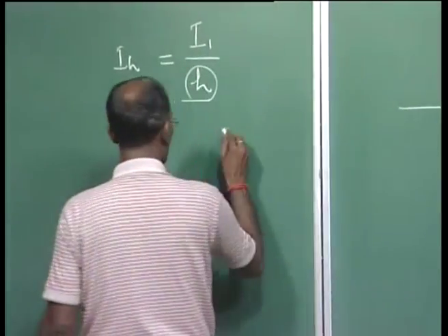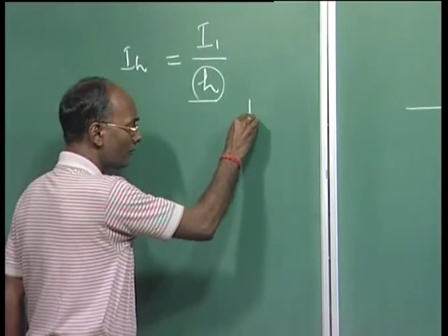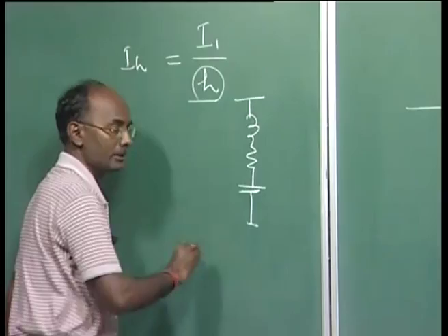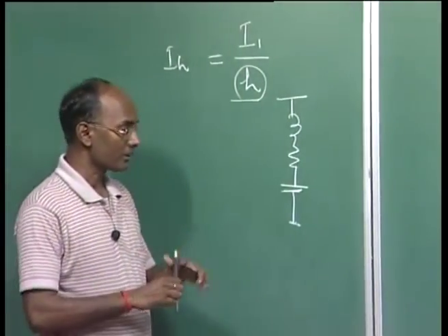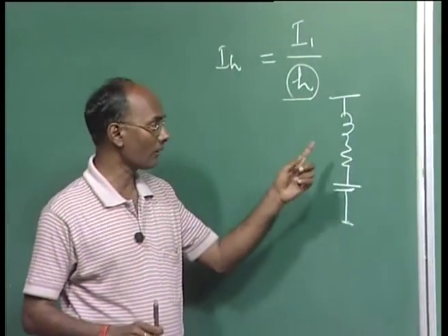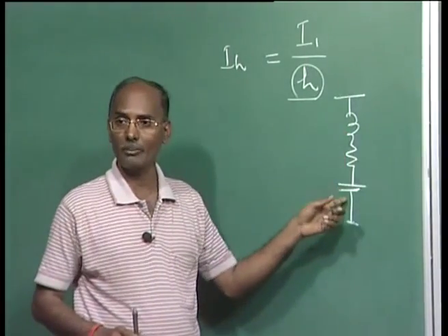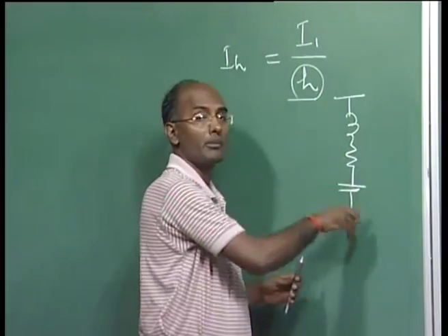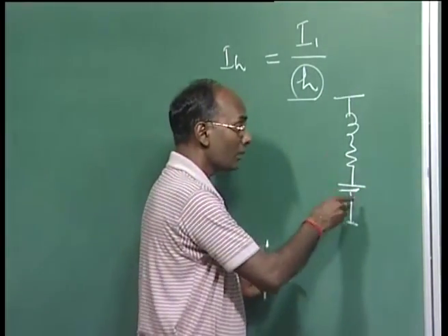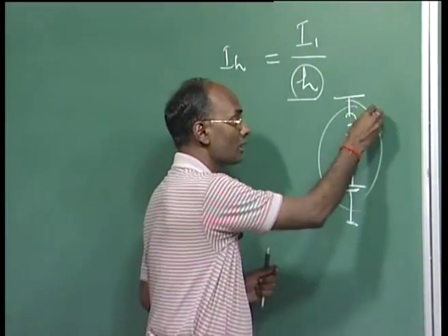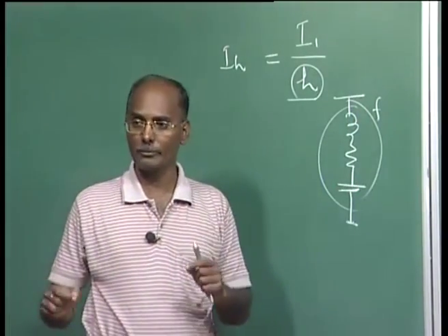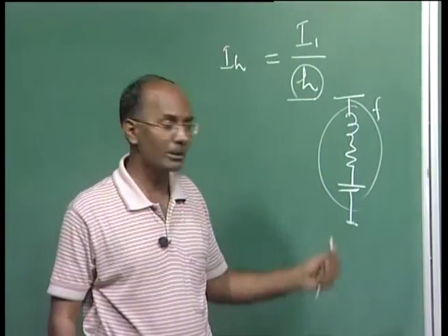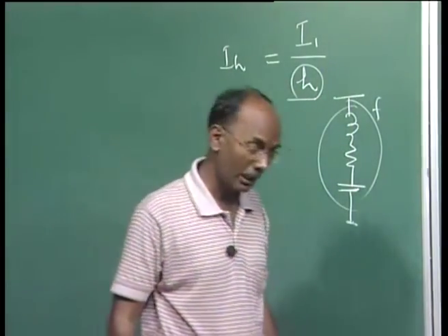I mean to say, if you are using this shunt filter, here it is an RLC circuit, at a particular harmonic the L and C impedances will vanish and we will have only the resistance here. So it will give the minimum impedance. But for the same circuit, if the frequency is F, the fundamental frequency, this circuit will behave like a capacitive circuit, which means it will provide reactive power support, and we need it.